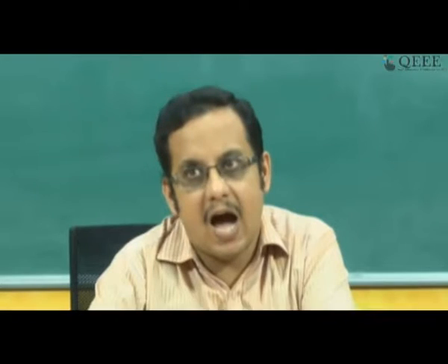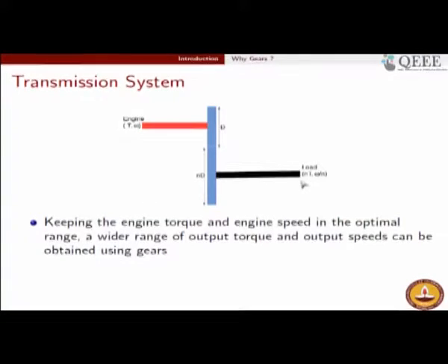What happens in the higher gears, let us say third, fourth, fifth gear, is that this n value keeps on decreasing, and as it decreases, the torque delivery is decreased. Because the vehicle is already running fast, the resistive load the vehicle faces is not so high, and as such you can come down to the driving torque requirements and increase the speed if you want.